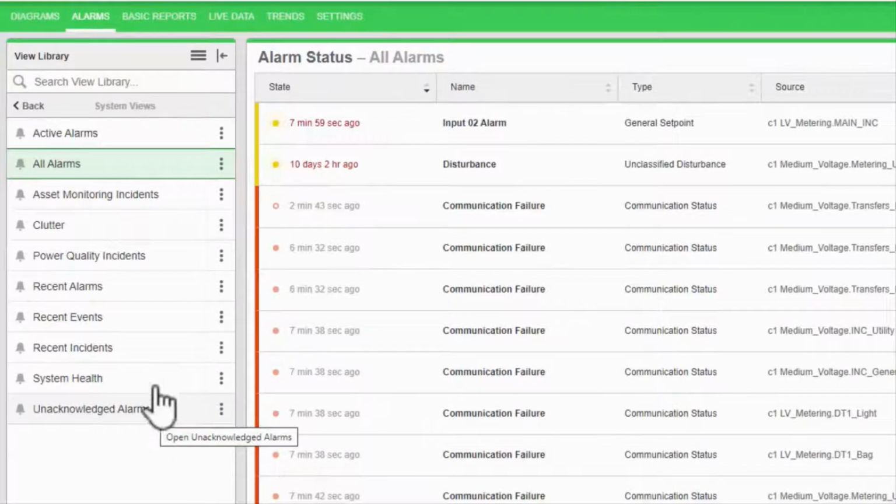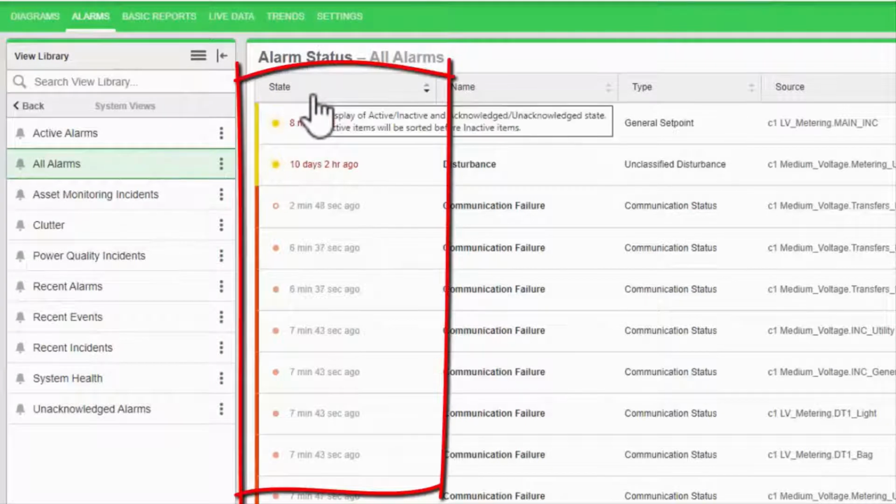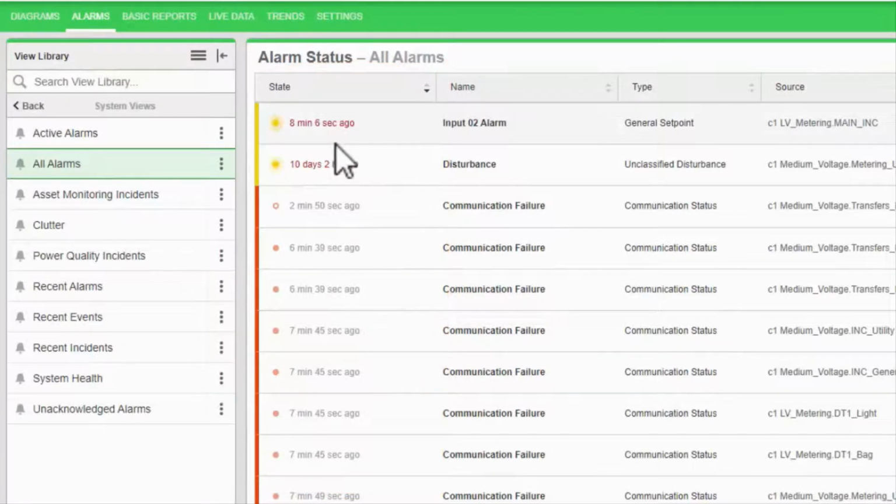These pages display the current states of the alarm tags. The state column tells me both how long since the alarm was last triggered, as well as its current state and category. By default, the indicator will be red, yellow, blue, or gray for high, medium, low, and event categories. This can be configured on the Settings tab. Also, if the indicator is flashing, its condition is still active.